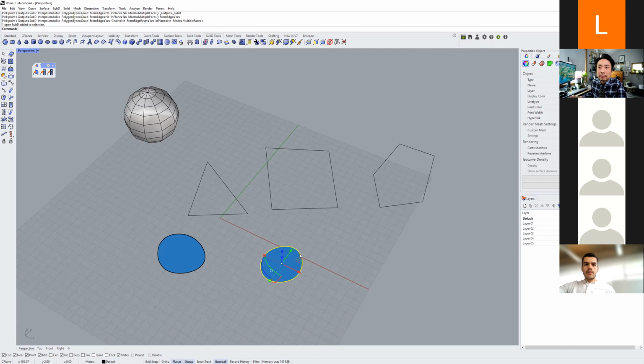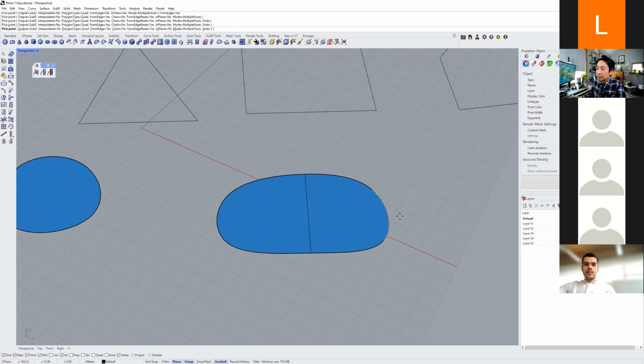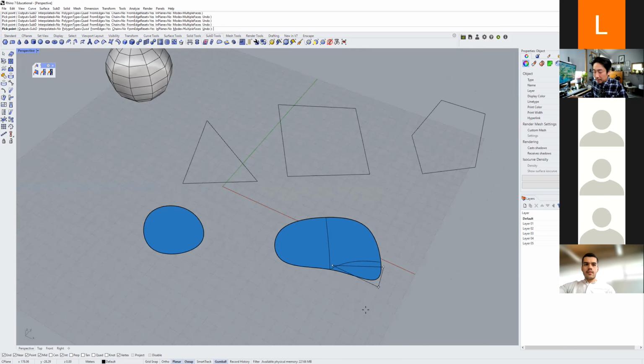Okay, we're gonna do one more time. Highlight the shape that you want to add to. Click on this one more time. So you don't see append anymore. So now you're appending to the shape that you just picked, and you want to continue building from edges. What that means is when your mouse moves close to a certain edge, you're building on that edge. So when you click, you're adding shapes to it.